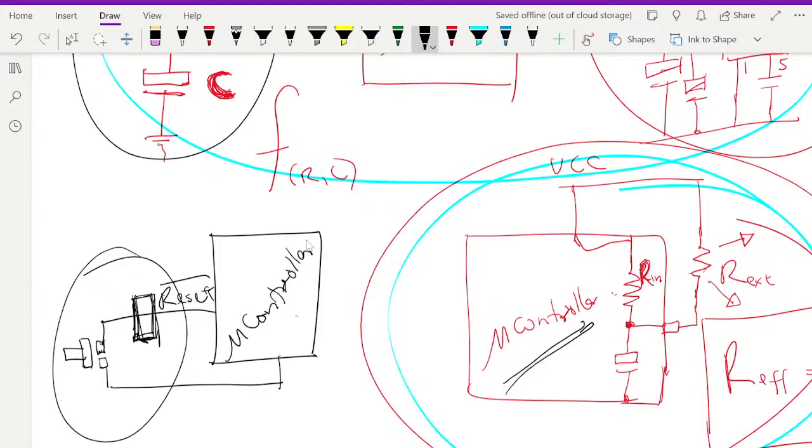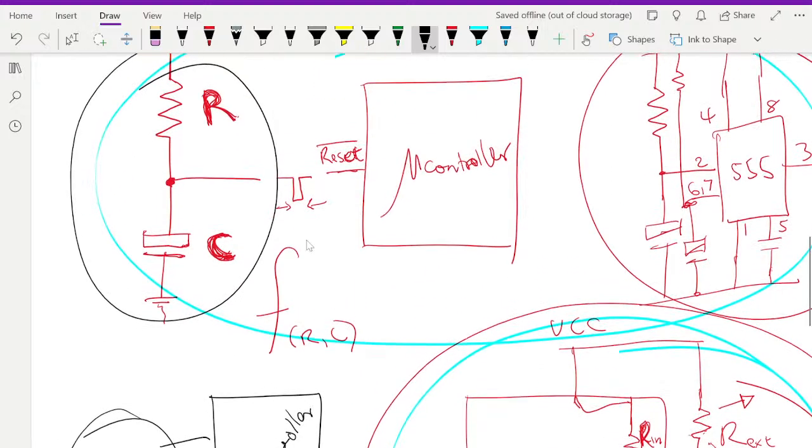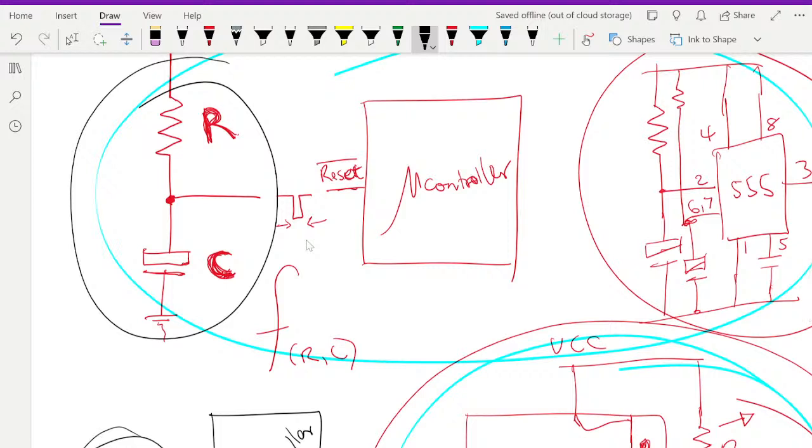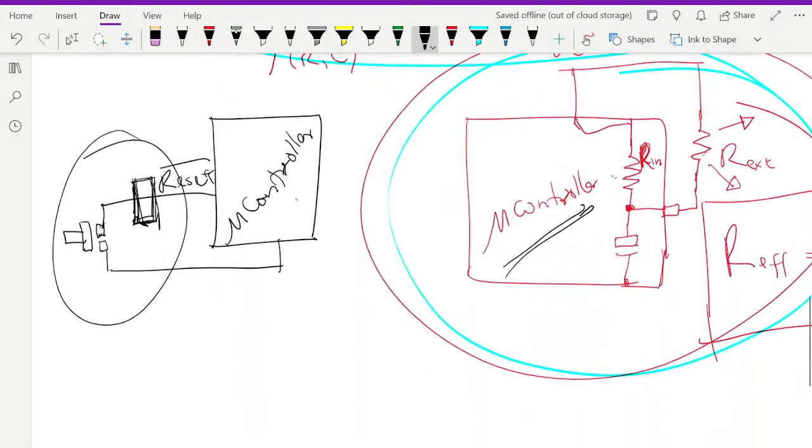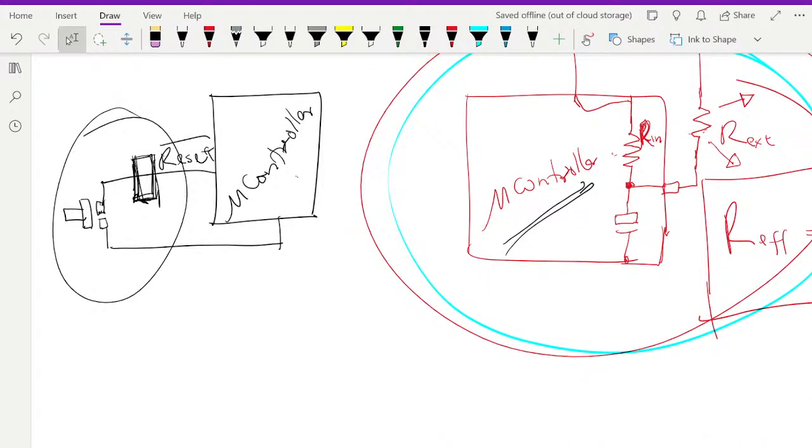It will measure the voltage, check when the voltage goes from 0 to a certain amount, and then trigger a reset. So that's a microcontroller. You have to write some code. The other one is using a resistor and capacitor connected to your microcontroller, and also using the microcontroller to run the algorithm and determine if it's the first time power comes in. Or you can use a switch, just push a button to reset the system.